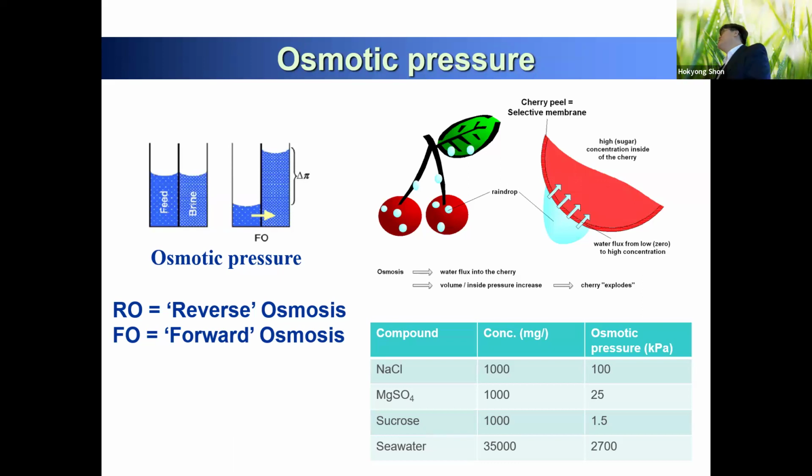That's why osmotic pressure is very important to design seawater desalination, because you have a recovery. Seawater is 35 gram per liter, and you have to recover 10%, 20%, 50%. So your salt concentration increases, your osmotic pressure increases, so the applied pressure has to be different, and then you have a different water flux coming out, right? So how can you calculate the varied conditions of salt, flux, and osmotic pressure?